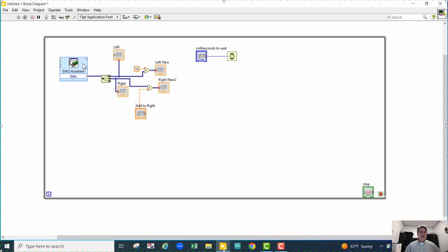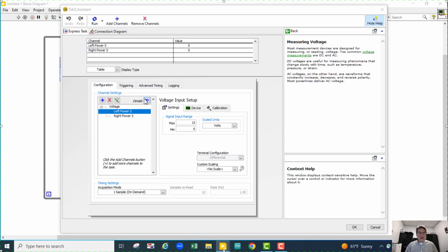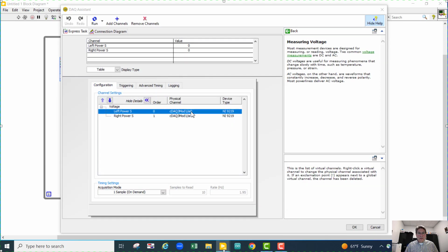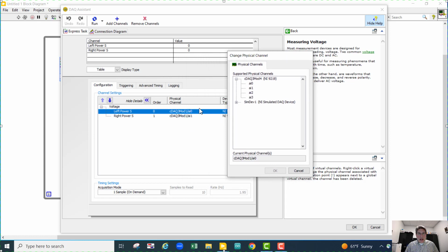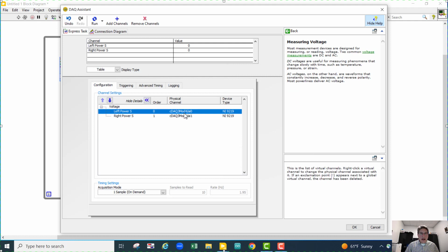So here's what you're going to do. You're going to double click on this. You're going to open this up so you can see, okay, this is supposed to be AI0. And now I'm going to right click on it. I'm going to say change physical channel. Now I'm going to click on which one again? AI0. And so what it's doing is, instead of clicking on it in slot 1, it's clicking on it down there in slot number 4. 1, 2, 3, 4. So I say OK. Notice how it changed from 1 to 4.